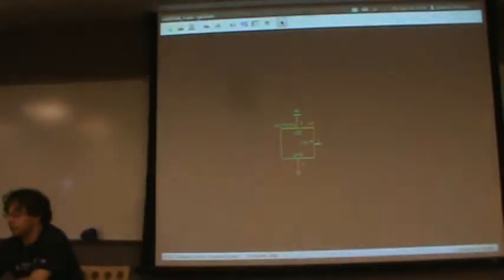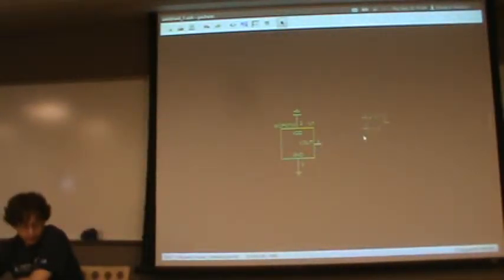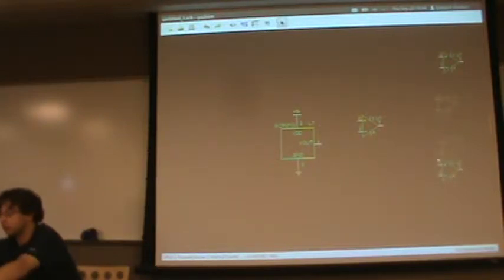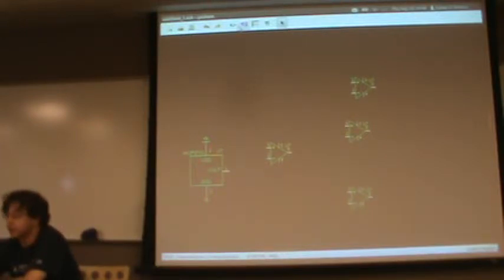So I'm going to drop in an op amp. So in my symbol library, somewhere in here, there's an op amp. It's just a pretty generic op amp. So I'm going to need, overall, 4 of those. And if you middle click, so scroll wheel click, while you're dropping things, you can rotate. So I'm going to drop one there, drop one there, one there, one more. Hit escape, escape again. So now I've got my 4 op amps, and I'm going to need some resistors. So basic devices again, and we've got resistors. There's a couple of resistor symbols. Some people like squiggles, some people like boxes. I'm not European, I like squiggles.